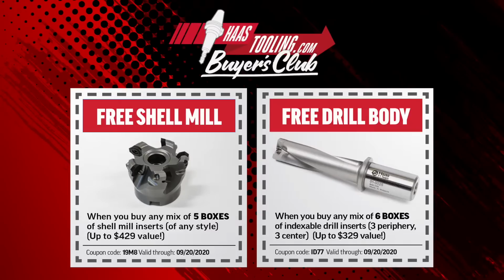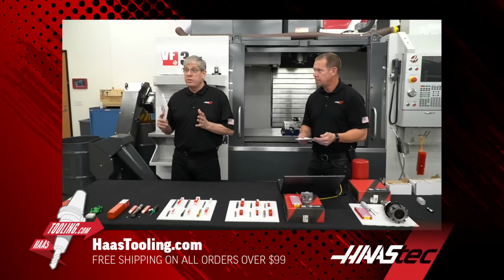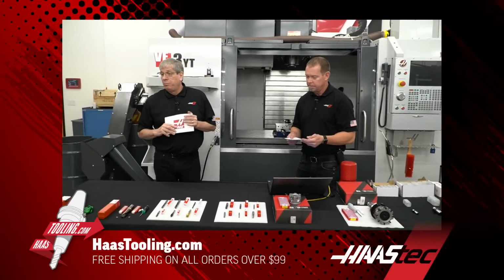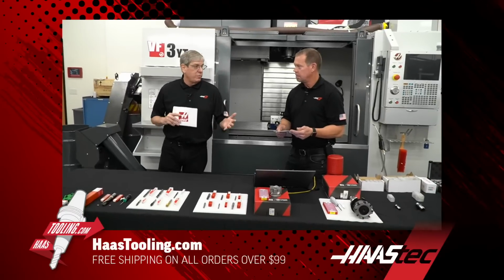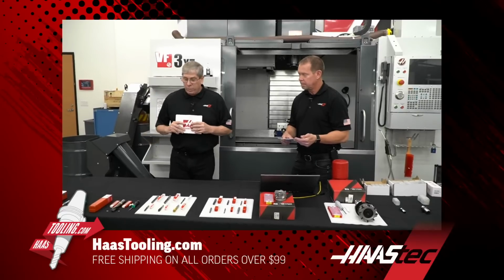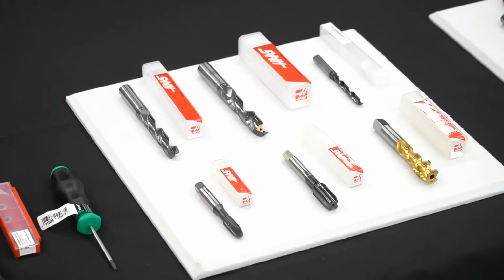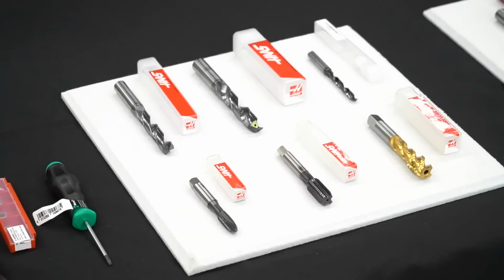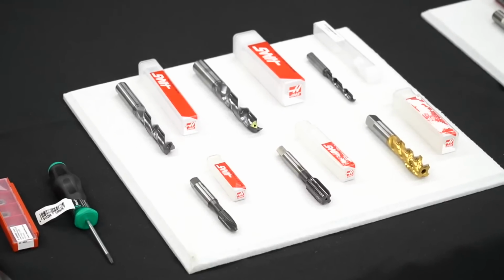So, solid carbide drills here in the back, there's a couple of examples here. We have 29 different sizes available, including all of the tap drill sizes for inch size threads. We offer these drills in 2 different geometries. Both geometries are Talon coated. That's titanium aluminum nitride coating, which is widely recognized as the best high temperature coating for drilling applications.